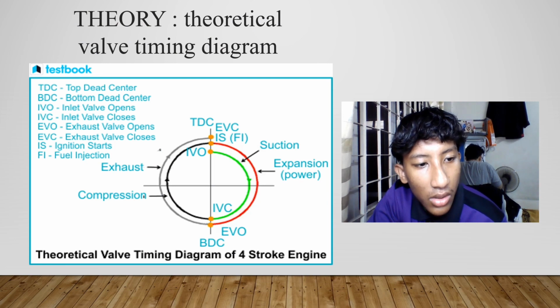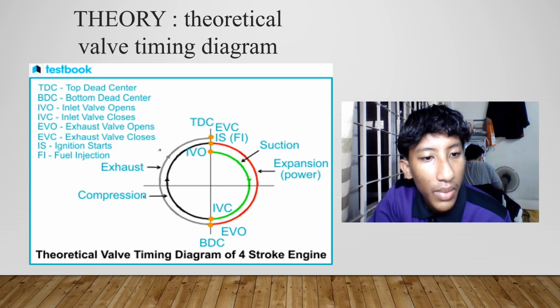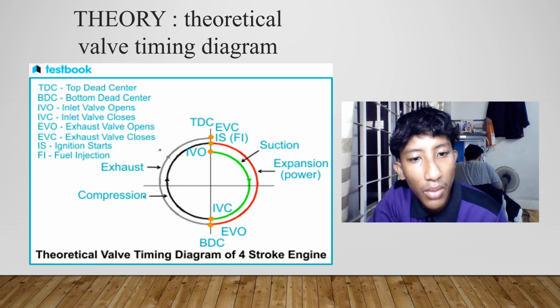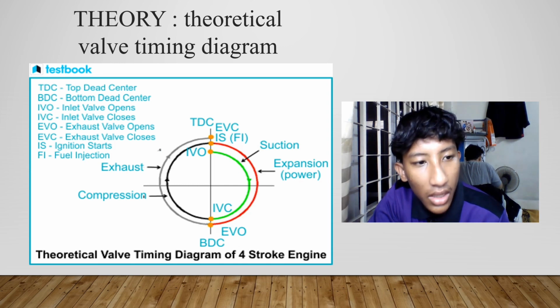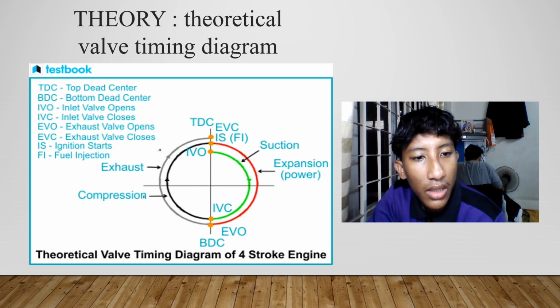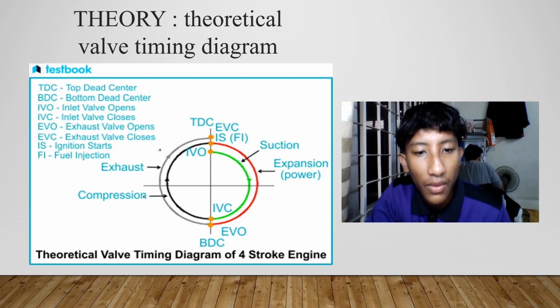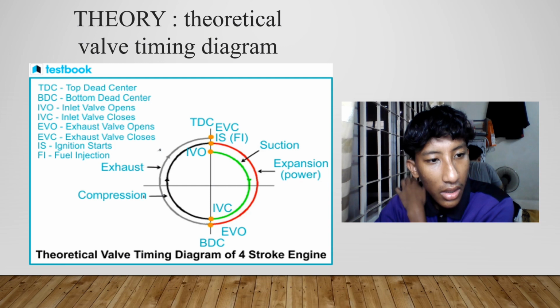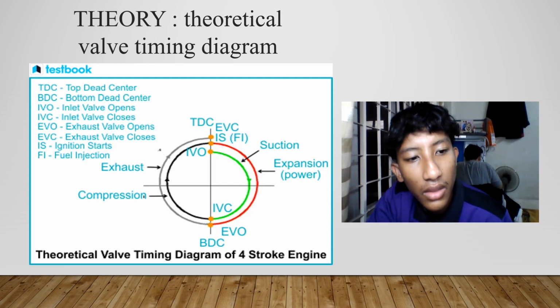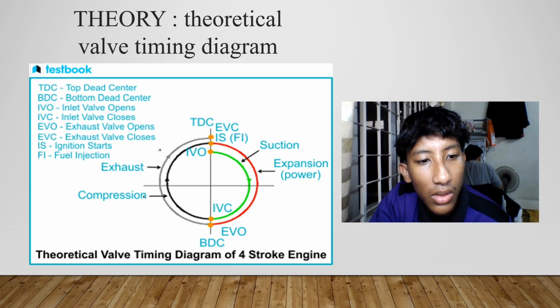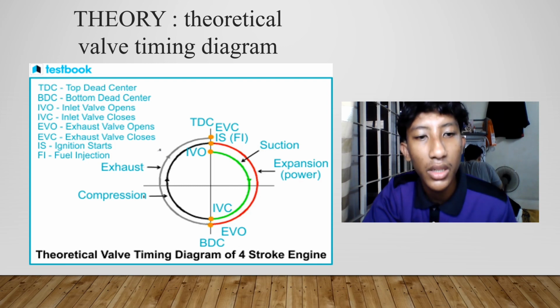At the compression stroke, the piston moves from BDC to TDC, compressing the air-fuel mixture in a petrol engine or fresh air in a diesel engine. This compression raises the pressure inside the cylinder, preparing for efficient fuel combustion. During this process, the inlet valve closes to seal the chamber for effective compression.